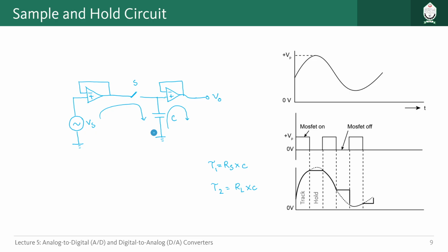So the RC constant will be quite high. Because of that, the discharging time for this capacitor will be very high, and ideally the capacitor will not get discharged much within the duration we need to hold the voltage across our capacitor so that we get the output, right? So this is the modified circuit, the improved circuit for these two issues we had.